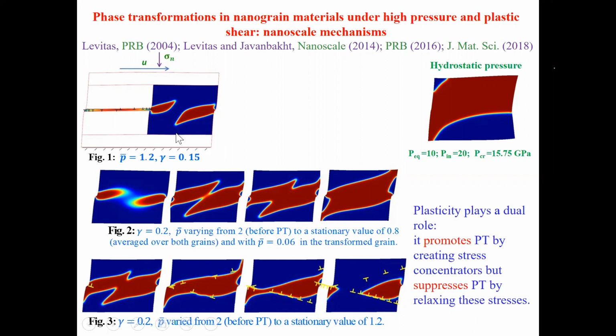And if we consider pressure averaged over this grain, it's just 1.2 GPa. So you see it's indeed more than an order of magnitude below phase transition pressure under hydrostatic condition, and almost an order of magnitude lower than phase equilibrium pressure. So it's deeply in the region of stability of the low pressure phase. And if we increase shear, you see that there is growth, coalescence, and quite a large red region, the high pressure phase, quite a large region transforms into high pressure phase.